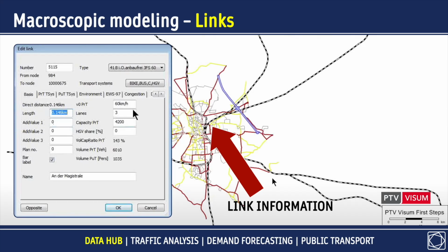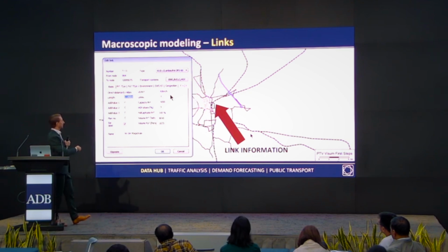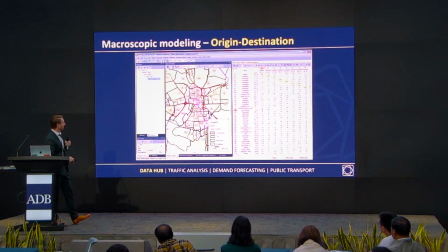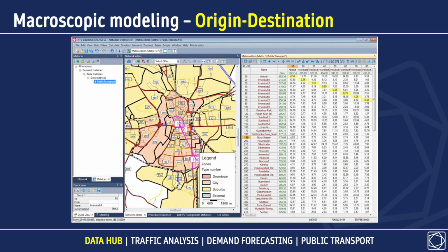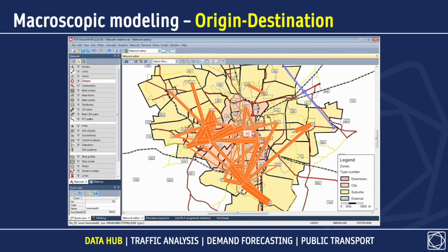And we can click on any given road and get information, the attributes of this road. So how long it is, the capacity of the road, how many vehicles can move through it in, say, an hour, the driving speed, and you have this for each and every road, which we call a link. And that becomes very useful when we get to the traffic analysis stage. You can also get data on your zone. So here we're clicking on zone number 10, and we can see related information.